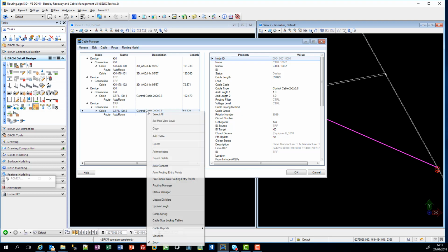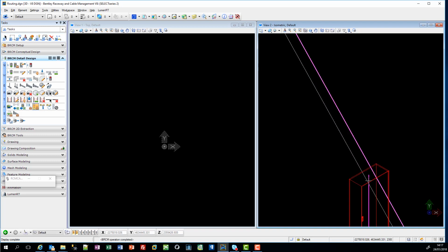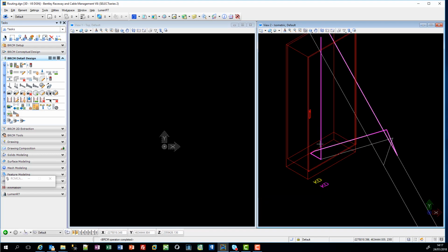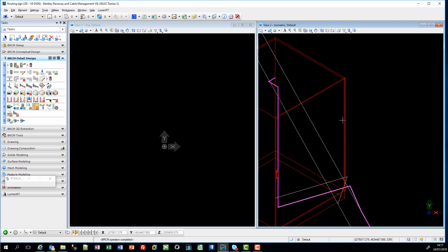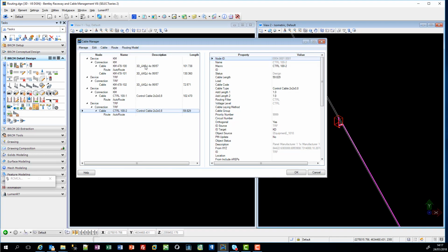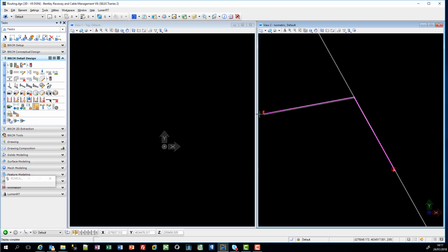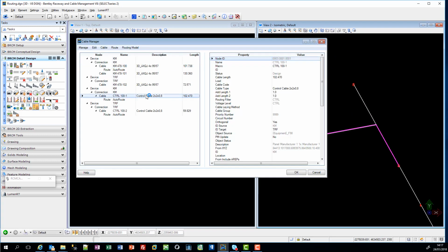And if I visualize, for example, the control cable here, it will show the connection from source to target using the conduits and the trench here. Or in that cable, it shows here the connection using the low voltage conduit and the low voltage line in trench system. It is possible here to check because there are some cables not routed, but let's continue and